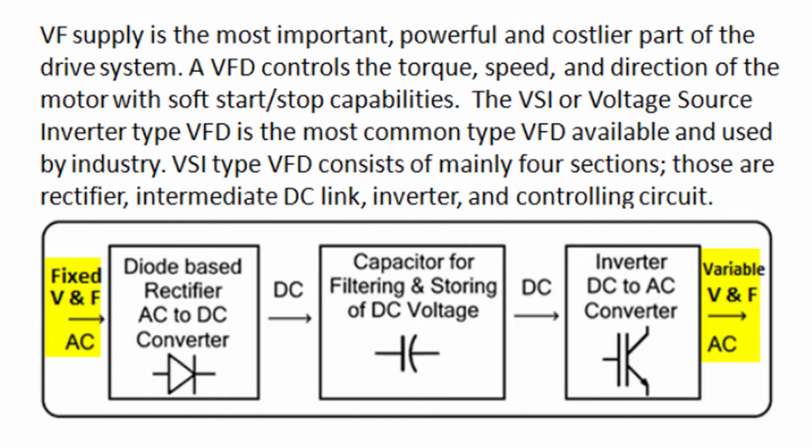Modern VFDs not only control the operating speed of the induction motor, they can also control load torques and the direction of the motor, and they also have inherent inbuilt capability of soft starting and soft stop if required. That soft starting and stopping can reduce the starting inrush of current and sudden jerks on starting and stop conditions, and that reduces electrical as well as mechanical shock and jerks to the motor driven system.